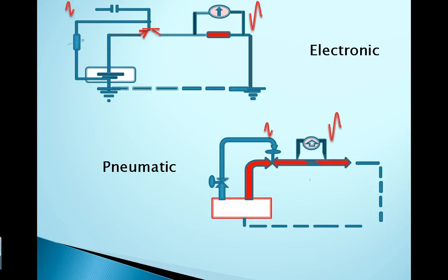So starting with the pneumatic one, just to recap, we have a compressor with a pressure of 100 psi, and this supplies air via a valve to an orifice and then out into the atmosphere. That orifice may be doing some work like spraying or whatever. If you put a pressure meter across the orifice, you're going to measure a differential pressure, which is a function of the opening or shutting of the valve. If the valve is fully shut, there'll be no differential pressure, and if the valve is wide open, then all the compressor pressure will be across the orifice and there'll be maximum airflow.